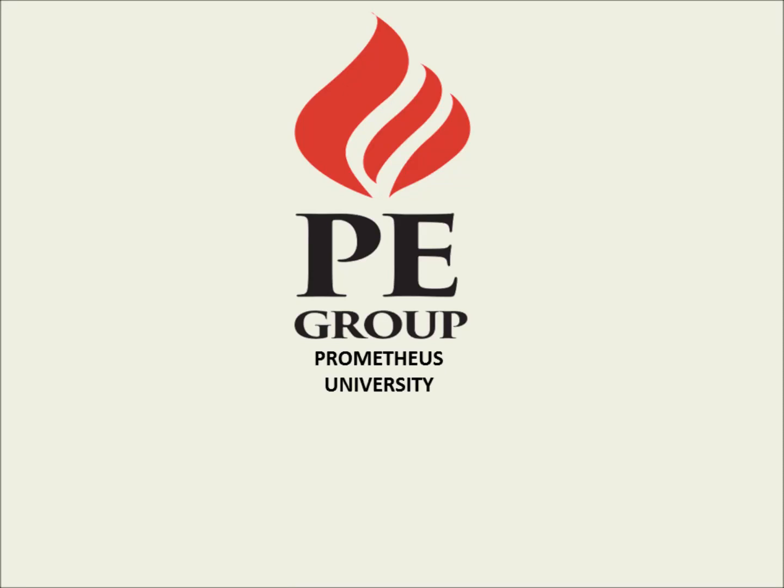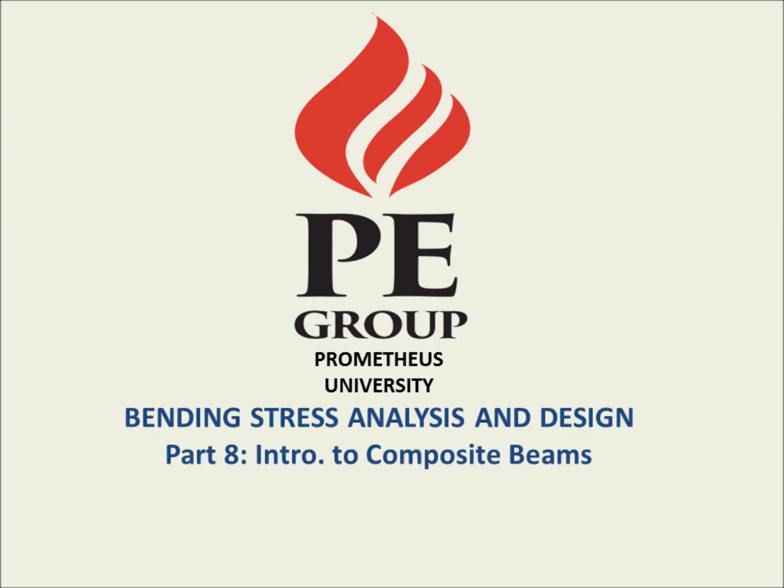My name is Ogiamien. In this part, which is part 8 in our 9-part series on bending stress analysis and design, we will be introducing you to composite beams. The main concept to come from this will be the concept of the transformed section. We'll talk about what that is, and we will determine some pertinent cross-sectional properties of this transformed section with a view to finding flexural stresses in the elastic range.